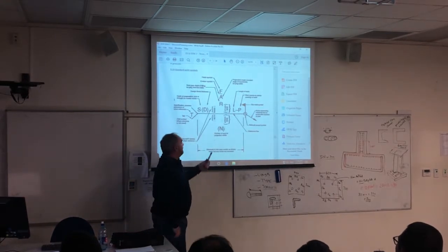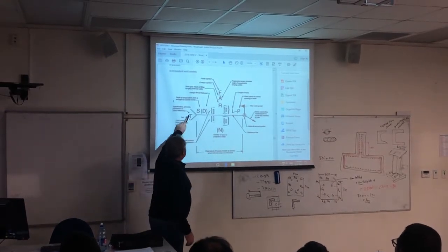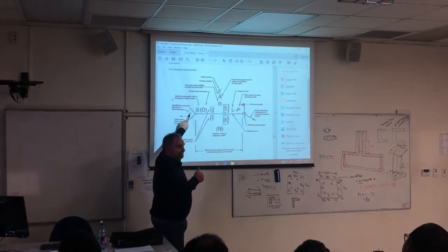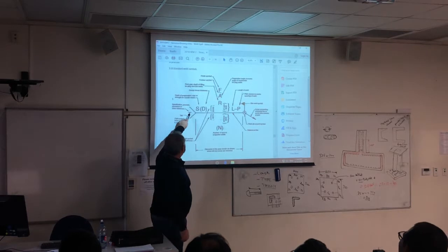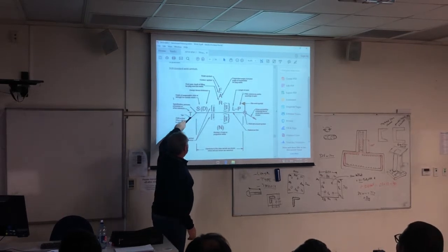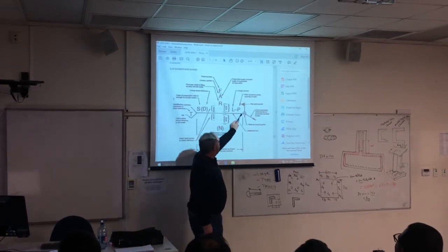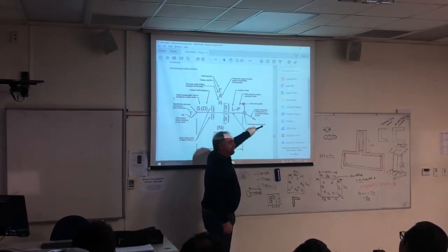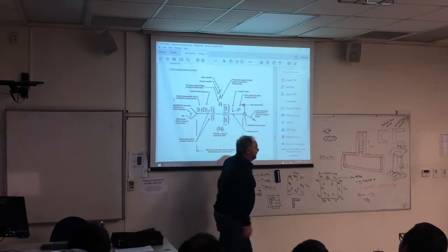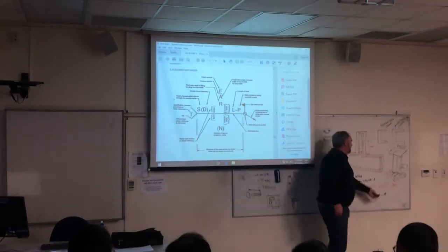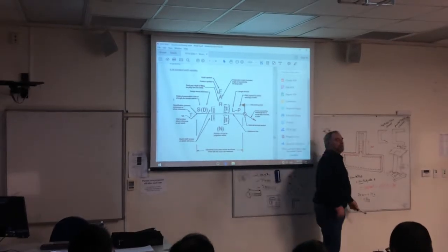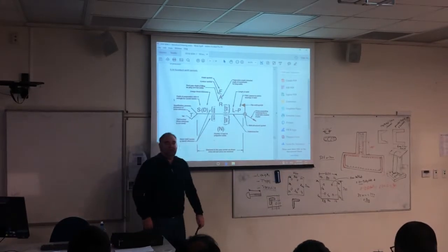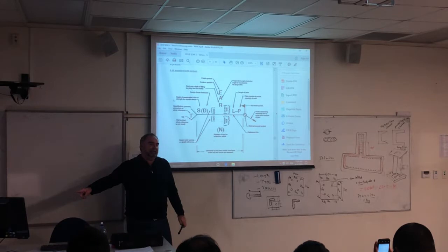So this is the symbol here. This T will be replaced by the number 6. Just told you. Okay? Put a 6 here, put that there. Put this line here. The circle means all round symbol. That means the weld is all round. That is the weld we're doing. You have to decide whether it's an all round weld or not. Be careful and look at the notes.